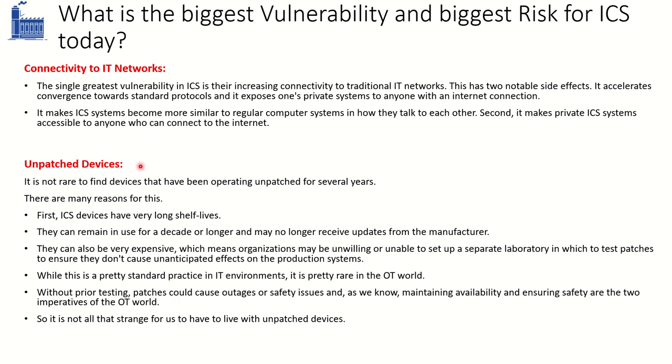Another thing I've seen is that in an ICS environment, if you upgrade a PLC or a device with the latest patch, the change is irreversible. You will have to manually take a backup of the PLC's code on a pen drive and then upgrade the PLC. And if you want to reverse the change, you will have to again go through a manual process of reversing the change, which is very cumbersome.